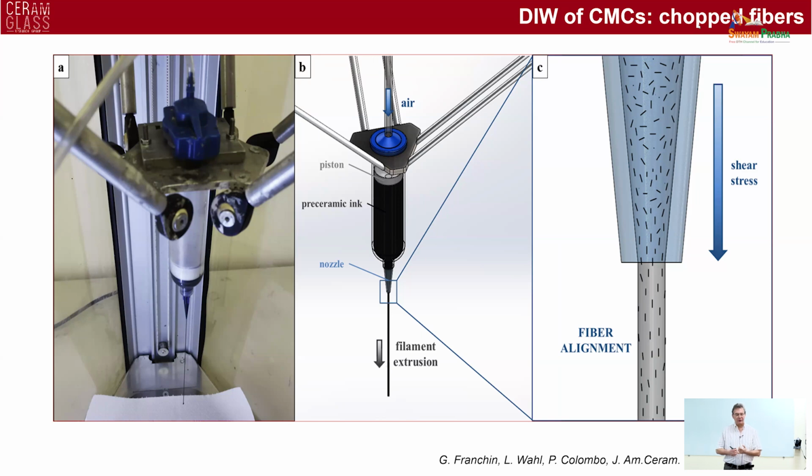We typically do not use an extruder with this application because we do not want to damage the fibers when they go through the extruder's screw. So this is quite an easy setup to manage. You simply have to make your feedstock in such a way that it contains the appropriate amount of fibers.